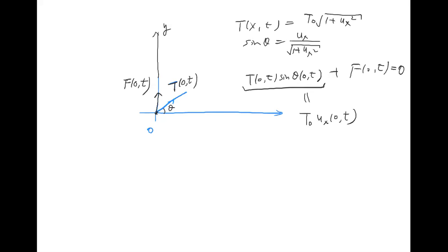So you get this, and that just means, in other words, the condition will be specifying... so if you subject the endpoint to a certain specified force that can be time dependent, this F0(t), then this is equivalent to a condition specifying the derivative of u sub x. So that's a Neumann boundary condition.